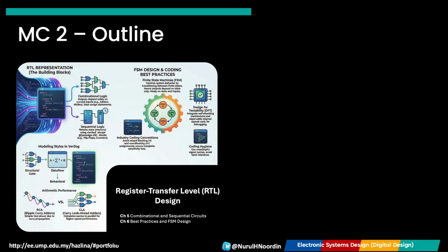In the context of digital system design, RTL stands for Register Transfer Level. It is the level of abstraction used in describing the operation of a synchronous digital circuit. At the RTL level, a designer defines the circuits by specifying the registers where the data is stored, typically flip-flops, the combinational logic, the operations performed on that data, such as adders and multiplexers, and the data transfers, how the data flows from one register to another.